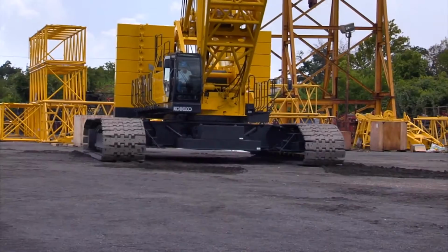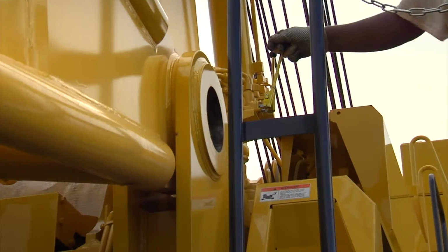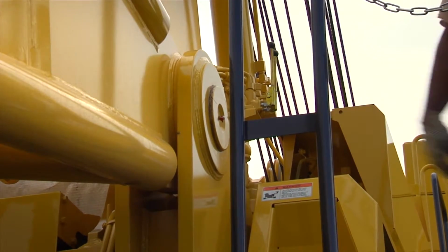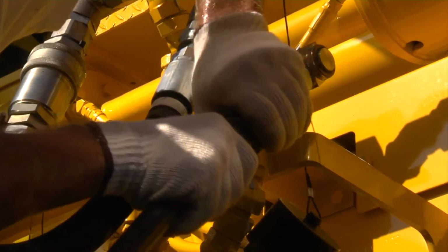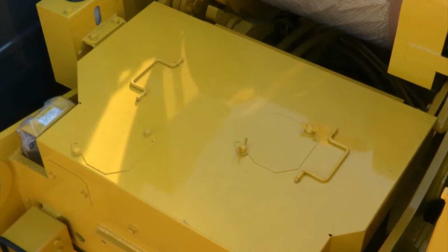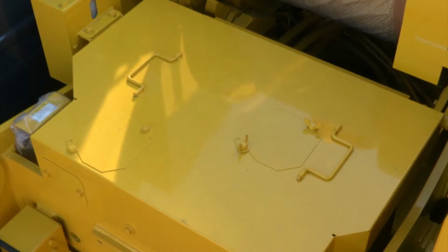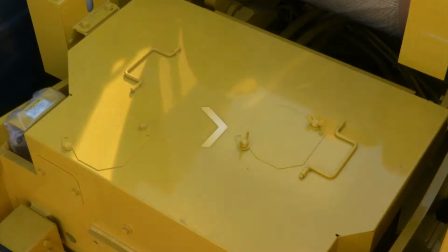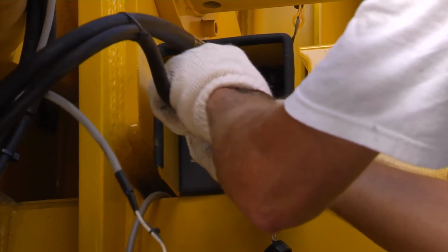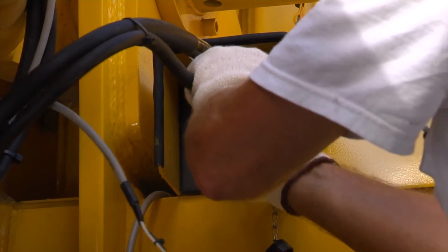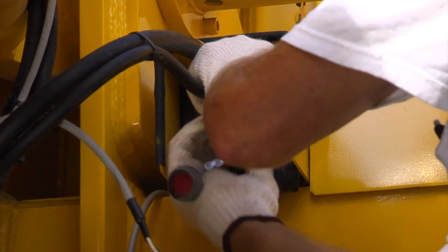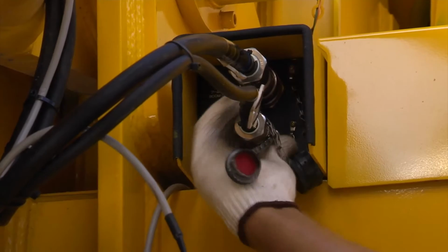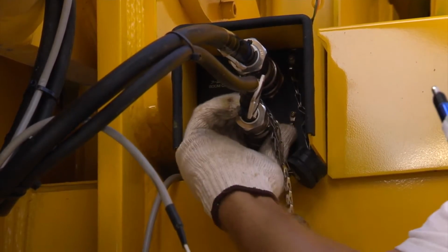Now, starting from the front center of the machine, we have the hydraulic actuated main boom base foot pins. We also have the quick connect couplers for the optional third hoist. Below these covers, there are 2 Kawasaki swing motors and 2 swing reduction units that can produce up to 2 revolutions per minute. There are 2 smaller covers that can be quickly moved to access the swing reduction unit oil levels. Mounted to the front area of these covers is the junction panel that's used to connect the attachment harness, and during the self-removal configuration, using the mast only, the angle sensor for the mast will connect here.